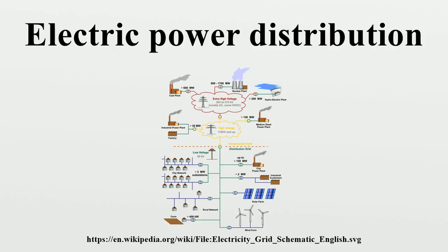International differences. In many areas, delta three-phase service is common. Delta service has no distributed neutral wire and is therefore less expensive. In North America and Latin America, three-phase service is often a Y service in which the neutral is grounded at various points. The neutral provides a low-resistance metallic return to the distribution transformer. Y service is recognizable when a line has 4 conductors, one of which is lightly insulated. Three-phase Y service is ideal for motors and heavy power usage.